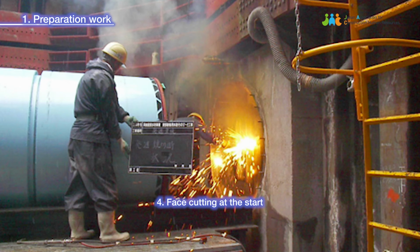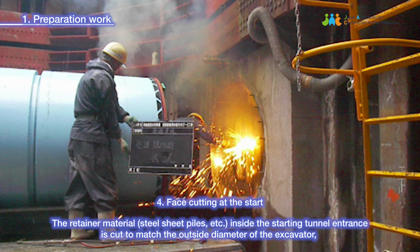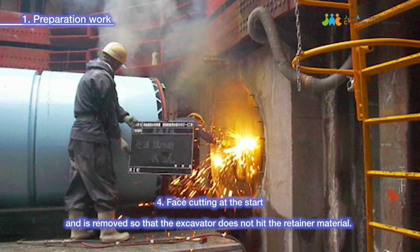4. Face cutting at the start. The retainer material, steel sheet piles, etc., inside the starting tunnel entrance is cut to match the outside diameter of the excavator, and is removed so that the excavator does not hit the retainer material. Gas welding qualifications are required for retainer cutting work.